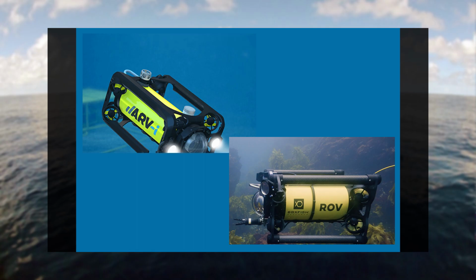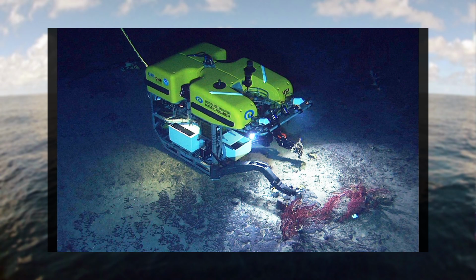Now let us see remotely operated vehicles and autonomous underwater vehicles. They serve as specialized platforms for high-resolution seafloor characterization, particularly in structurally complex or logistically constrained environments. Equipped with multi-beam sonar, side-scan sonar, and high-definition photogrammetric cameras, these systems collect co-registered geophysical and optical data.